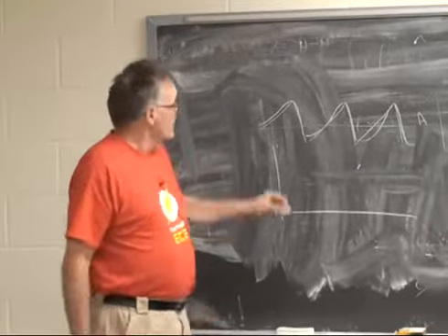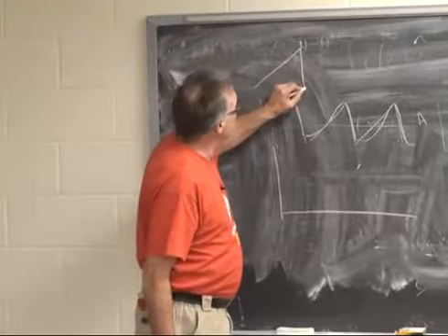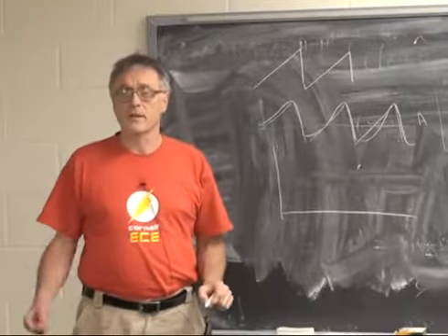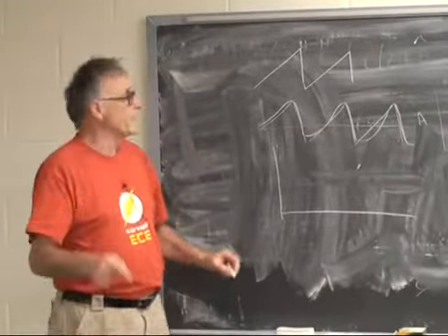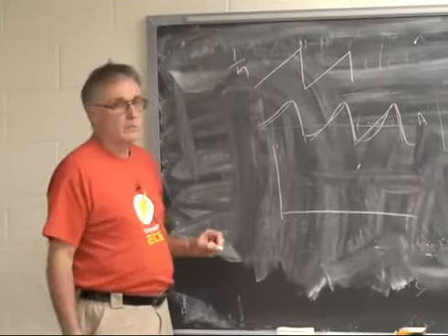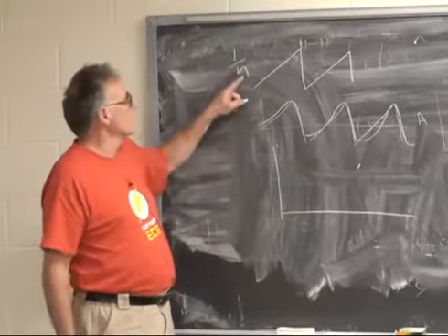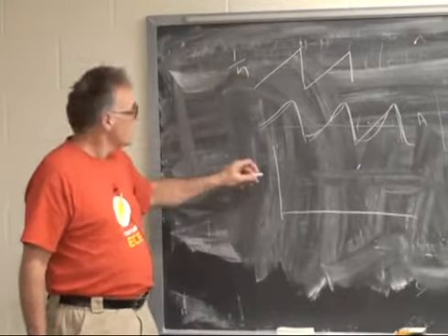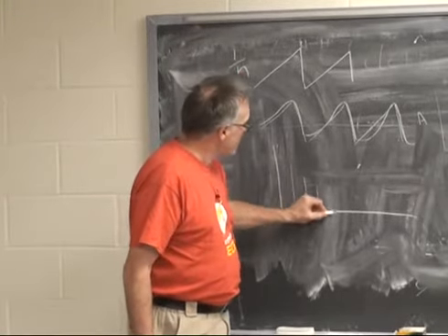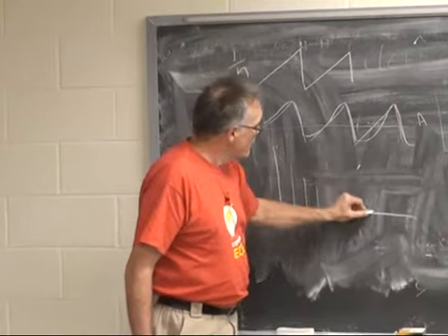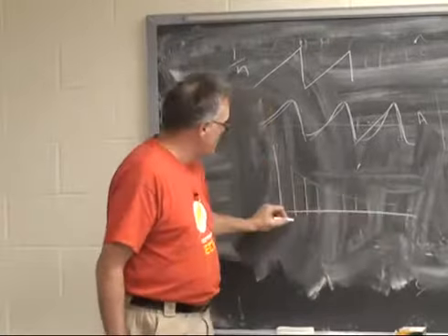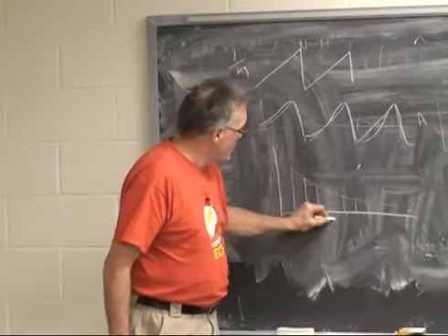In fact, it has all harmonics, and it has a discontinuity. Whenever you have a waveform with a discontinuity, it says that the spectrum can drop no more quickly than 1 over n, where n is the frequency. So the spectrum has to be at least this large. So there's going to be a series of lines that drop no more quickly than 1 over n, and correspond to all harmonics.